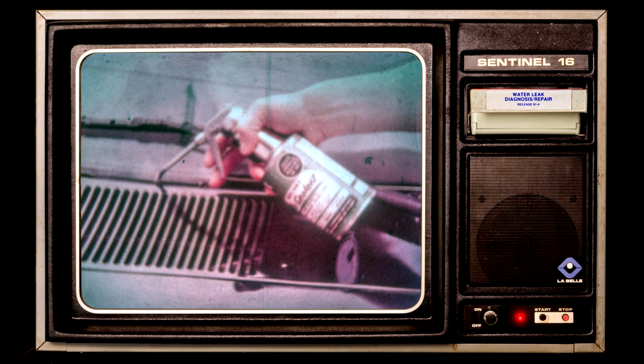Leaks in urethane applications should be sealed with either of these 2 products: Kent Industries Wet-Dry Resealant or 3M's Window Weld Resealant. These sealants remain soft and pliable to cushion glass movement, thus maintaining an effective seal even when the glass and body panels are flexing.